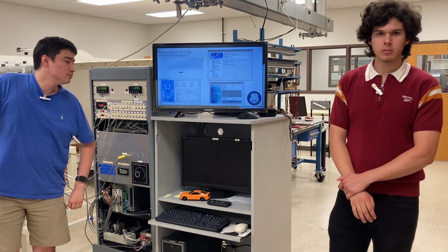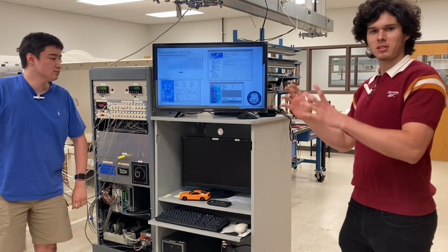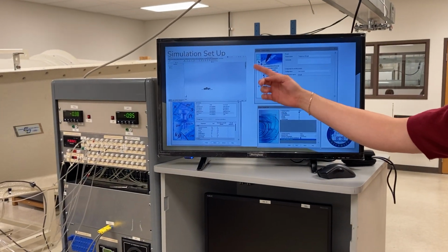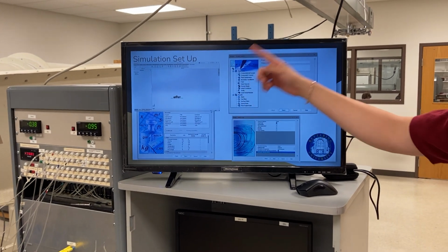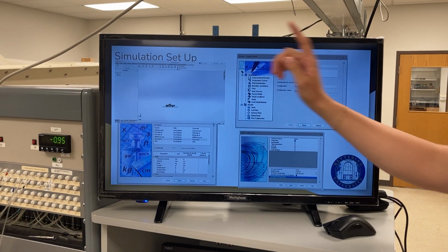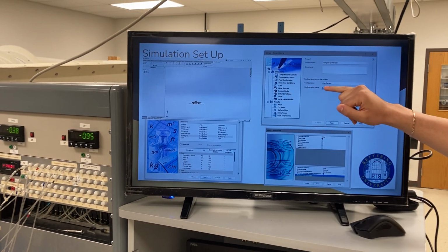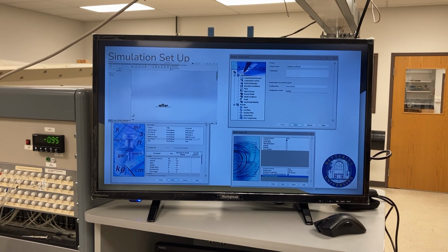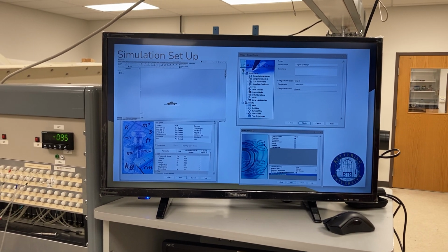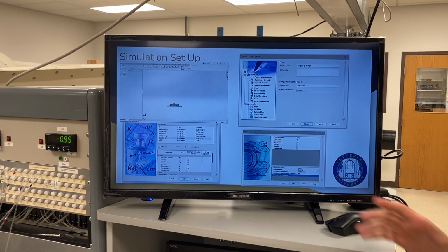Okay, so for the setup of the simulation, if you want to come up close since it's little, first you import your model into your desired modeling software. It has an automatic setup for the simulations. You click Wizard up top here, and it opens up a few different menus where you can select your conditions, your units, your velocities, your inputs, your everything.